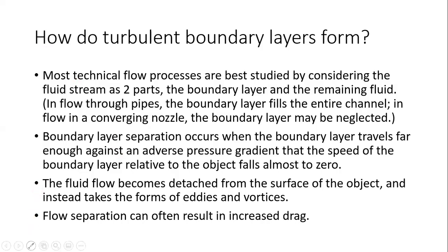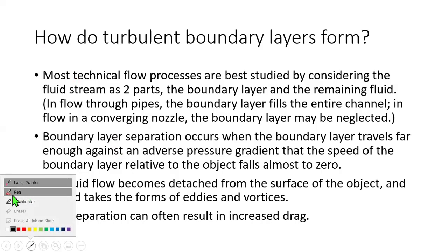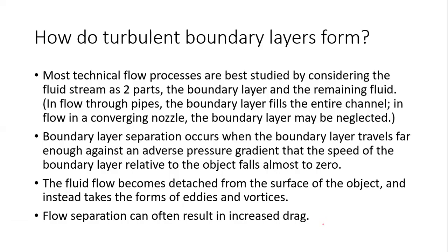What we are trying to say by that is, if I have a pipe, or let me start it this way. If I have a surface here, recall that we said the boundary layer is going to go like this. If I have a pipe, I have two surfaces, so there's going to be another boundary layer at the top here. So what they're trying to say is that there's a point where the boundary layers meet. There's a point where all of the fluid is going to be affected by the surface. So when the boundary layers meet, everything after it is going to have an effect coming from the solid. Because remember, we said the boundary layer is the region where the fluid is affected by the solid surface.